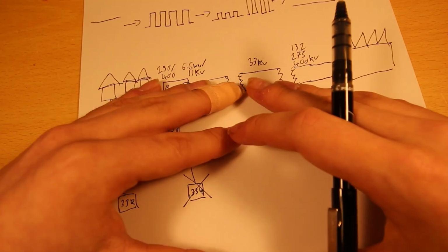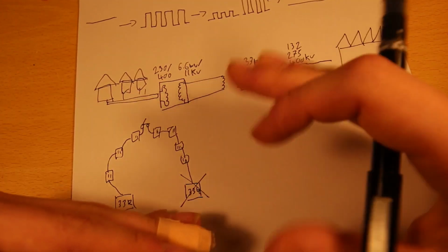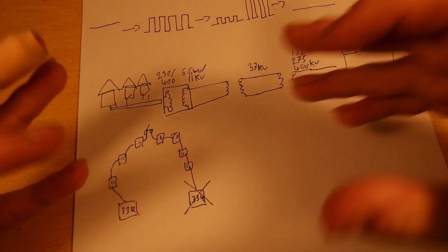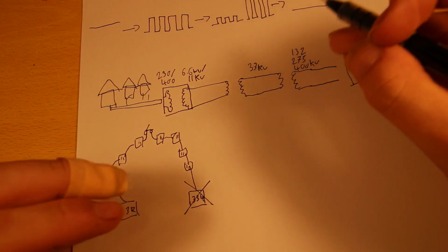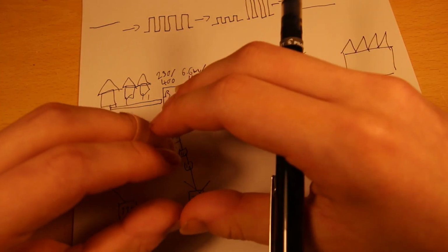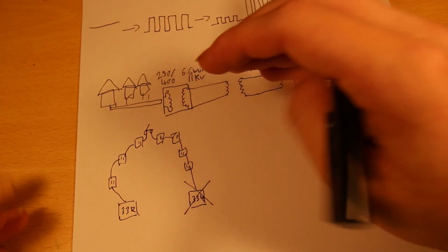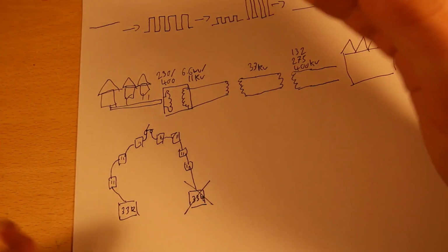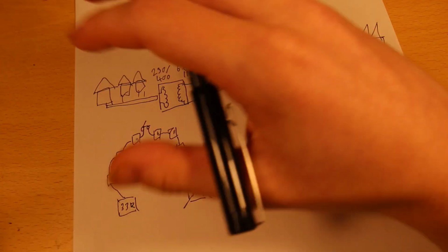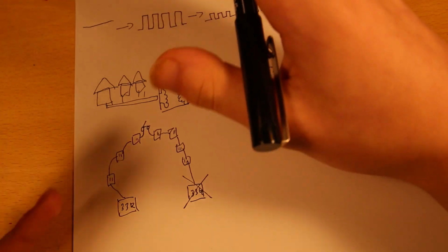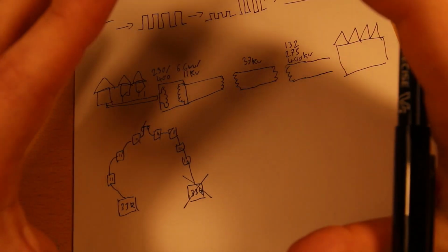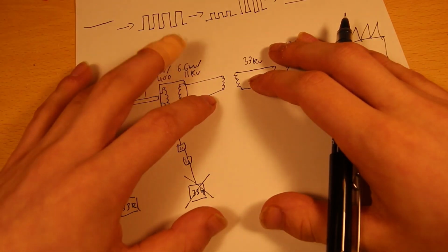We had the technology in order to make AC and DC swap them back and forth so easily and efficiently enough that it was actually worthwhile. So a lot of the big interconnecting power lines now that run from, say, Norway to the UK, there's one, that's DC. Or they're building one that goes from the Highlands to Shetland. That's DC, because the parasitic losses are higher. Let's now explain parasitic losses. Actually, no, let's not do that, that's complicated.